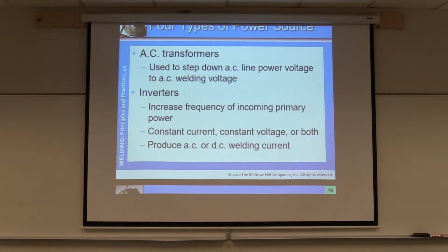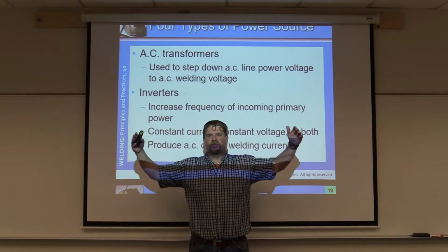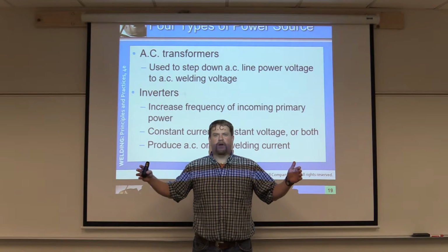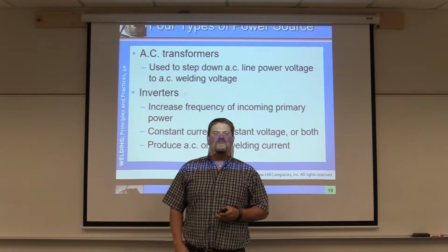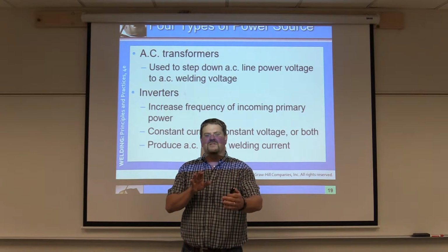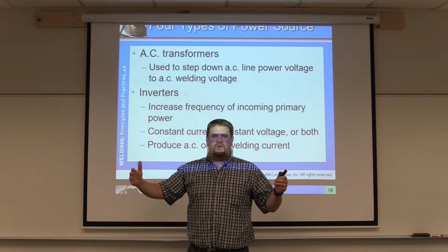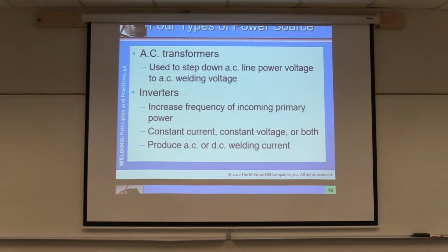All right, inverters. Now inverters have really picked up. It's amazing. 20 years ago, and we have some out in our shop even, you'll have this machine that's this big. Being a welding machine, it's huge. And then you go to the back and you'll see one of the newer Miller XMT 304s, and they're only like 40 pounds. They put out just as many amps and volts as that big welding machine does. So we've really condensed, we've been able to invert and step up the frequency of the incoming primary power.